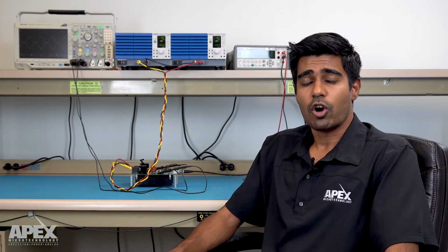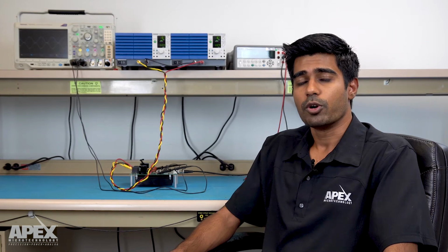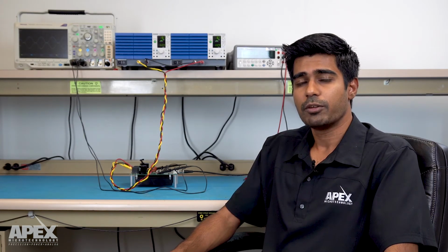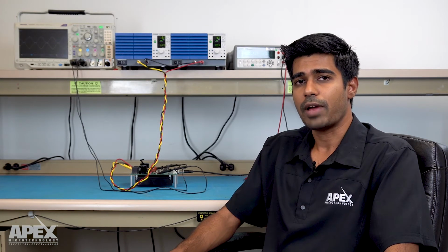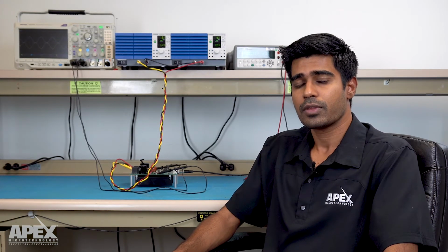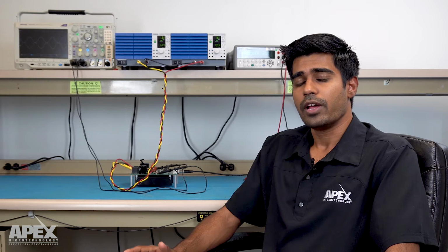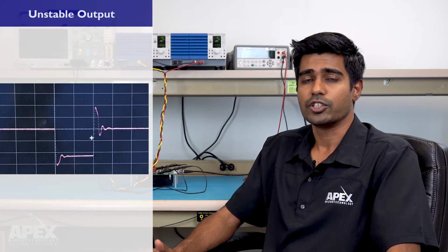Next, I will talk about overvoltage protection at the output of an amplifier. A power operational amplifier should never be stressed beyond its absolute maximum supply ratings. Conditions where there is a change in the current for an inductive load or if there is a mechanical shock for a piezo device can result in voltage flybacks from the load.